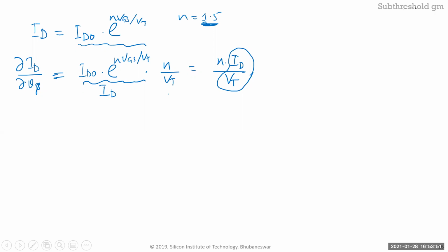If I get that, I can build high gain amplifiers with very low current if it is low frequency. If I want to operate at gigahertz, then yes, I have to operate it in saturation because I have to pump tons of current, and that's when I need it to be operating in the saturation region, inversion.